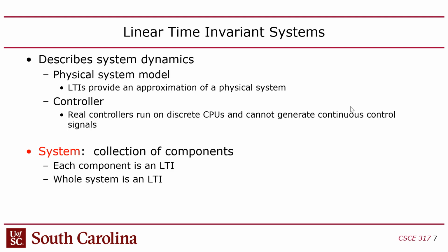In this class, I'm covering control theory because I wanted to introduce the effect of computing on control theory. There are some issues when you design a digital controller: you have to discretize time. You have this time step, and there's a certain amount of time you have to calculate your control decisions. If your CPU isn't fast enough, or your code isn't optimal enough to meet that execution time limit, then the system can fail.